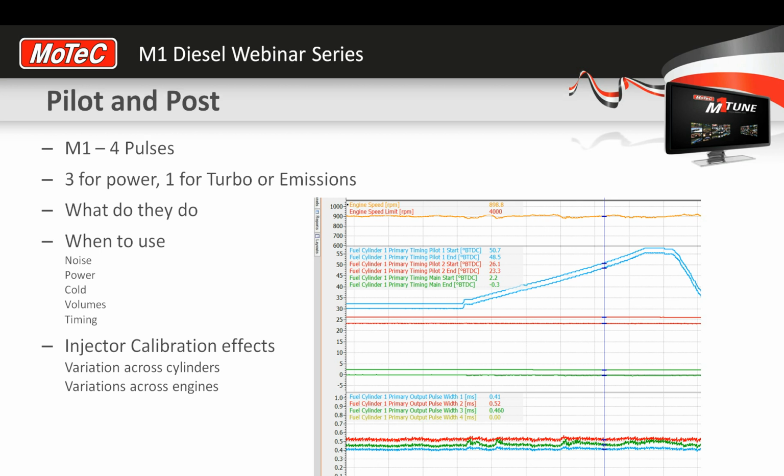The way to make the pulse width longer for the same amount of fuel is to drop the fuel pressure lower than perhaps the OE runs it. For example, OE might run it at 40 MPa. If you drop yours to 30 MPa, it will deliver the same amount of fuel if your injector calibration slope is right, but the pulse width will be longer.